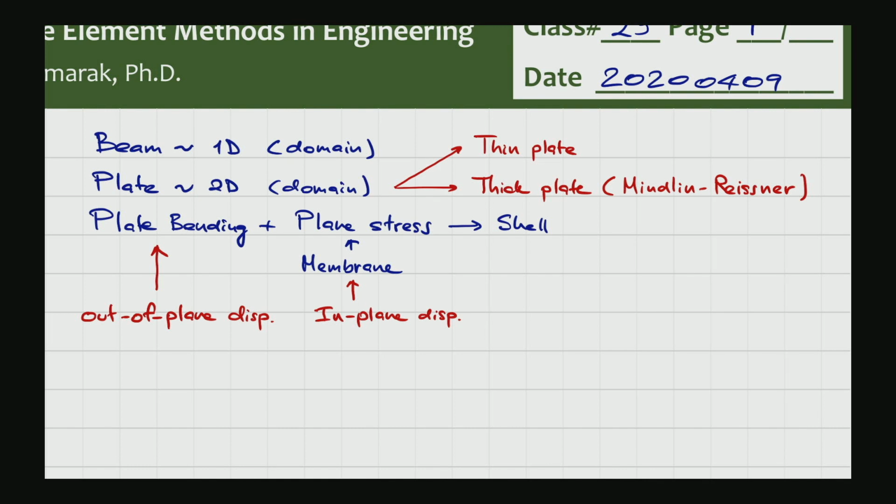Well, if you want to make an analogy, the thick plate is associated with the Timoshenko beam. The Timoshenko beam accounts for the shear deformation. For the plate, the Mindlin plate incorporates the shear deformation as a component for the deformation calculations.